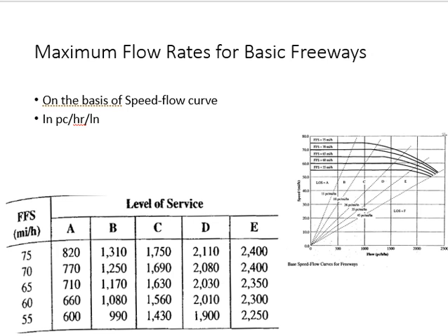Okay, this is the line of A, right? If I go above it, then I'm not at level of service A. If I draw a line from here and get this flow rate, then when I'm above the line, my flow rate will be more than this. Will my level of service be A? No, it will be something else. So wherever the line intersects the curve, this is the maximum flow rate for this level of service.